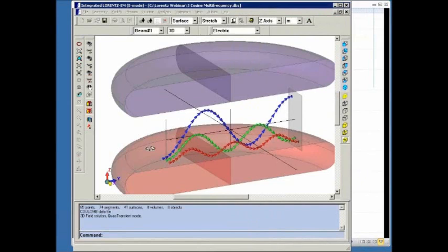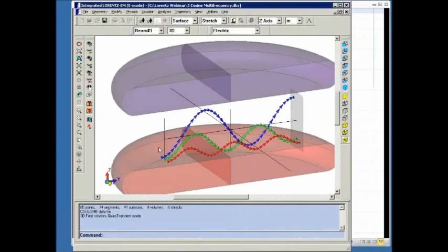And what you're seeing here are three separate emissions. The blue emission starts at time t equals 0, and it experiences the 150 kilohertz sinusoidal variation. And then after 10 microseconds, it actually hits this rectangular surface, which is a collector, so it ends. The second emission begins at time t equals 10 microseconds, and it sees the 210 kilohertz signal. And the last emission begins at 20 microseconds, and it sees the 300 kilohertz time signal. And that's easy to do.